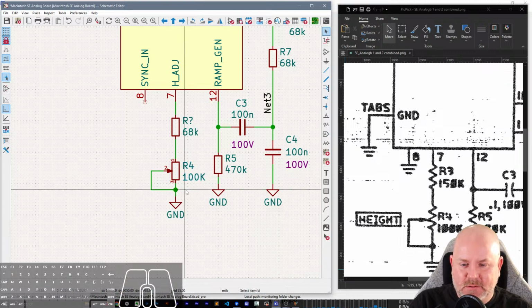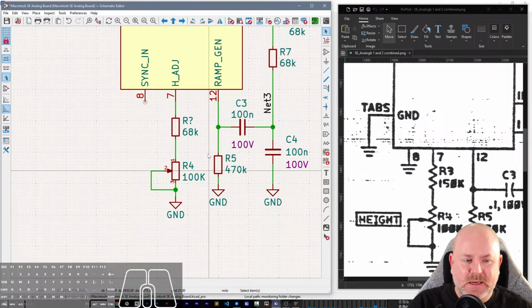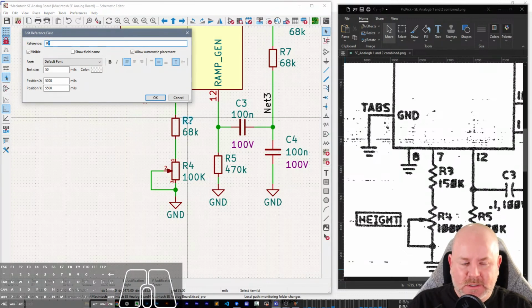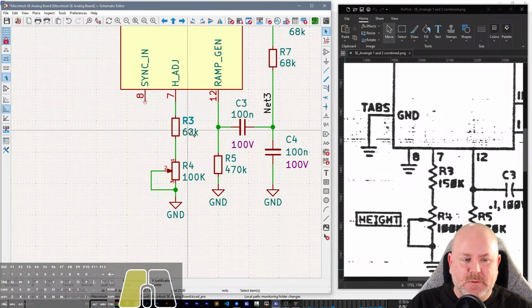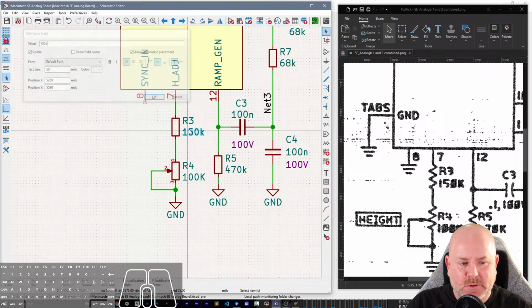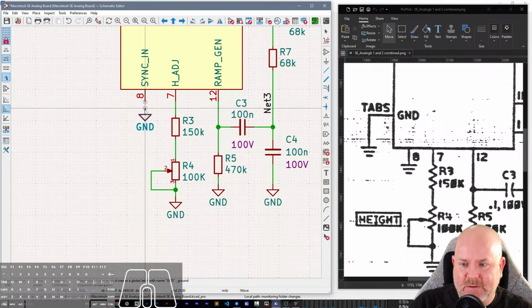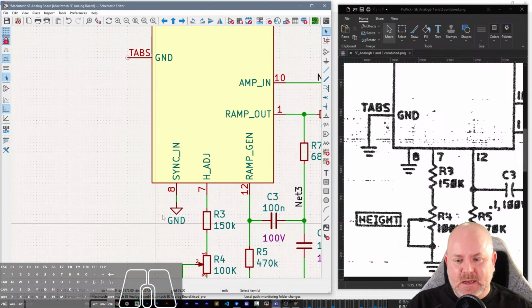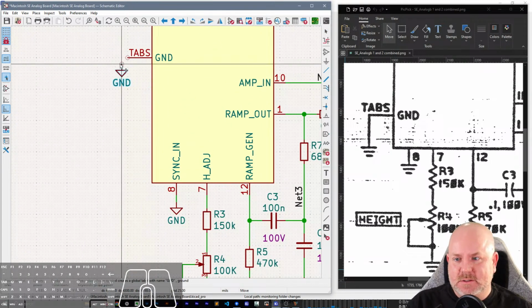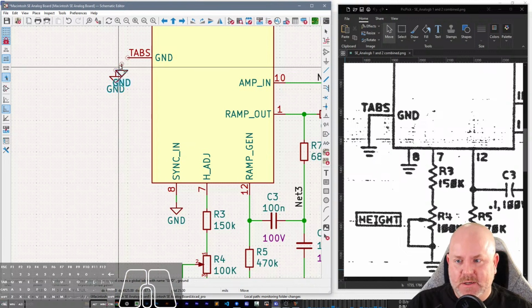Regex does not work on everything, but it does work on net class assignments, which to me is nice, it's powerful. But I don't think it's very clear to people that that's how the net class matching works, which is actually a video topic that I have on my list, because I have been very vocal about how unintuitive the whole net class assignment thing is.